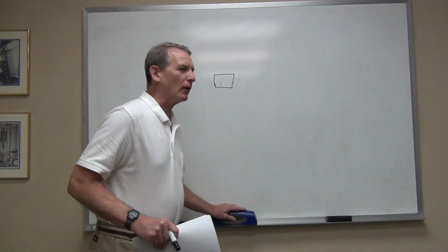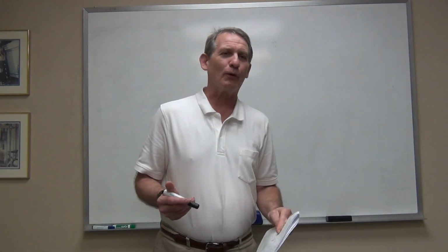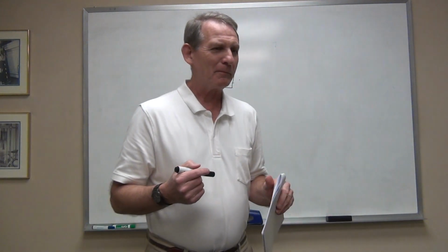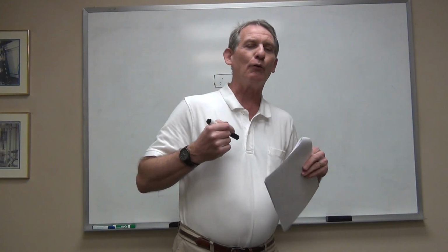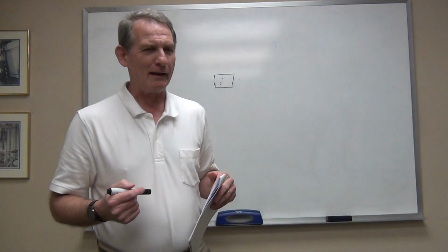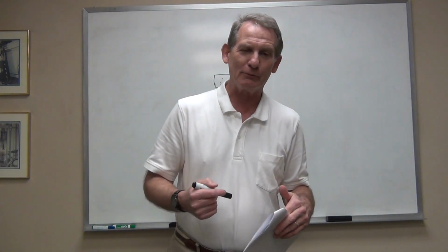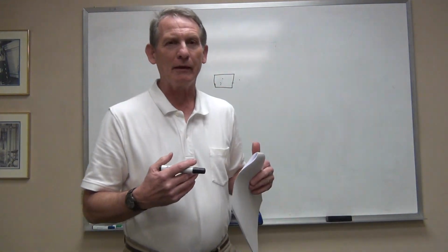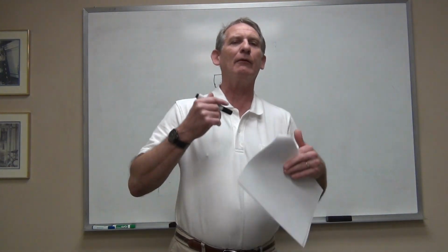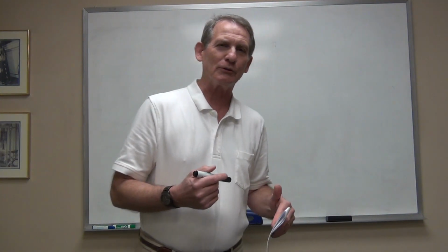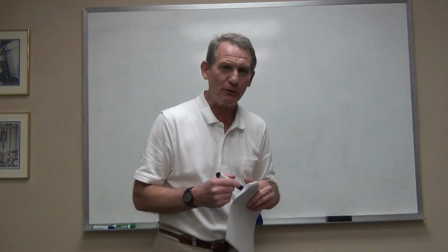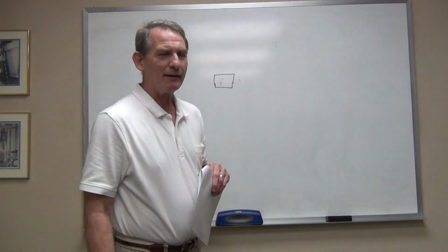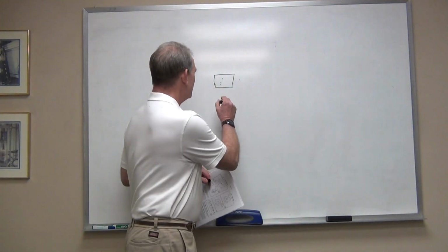What if you need 24? Well, if you need 24, you're working on something incredibly complex, and you're probably overdoing it. I have worked on some very complex machinery and equipment for aircraft where a single drawing might have 20 pages to it. I don't think I've ever seen them do what they're suggesting here in the standard that you can do, but you can do it: if you need that 24th symbol, you double the letters.